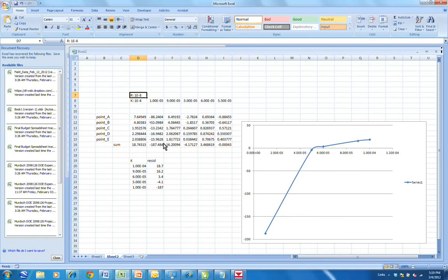You'll have another little grid here and come up with a K and R that best match the heads and hopefully match the discharge. What I would do is plot the recharge and the base flow, create another plot like this one, and use that to help guide your estimates of the recharge that you set up in order to match the base flow that you see. And that'll be the procedure.